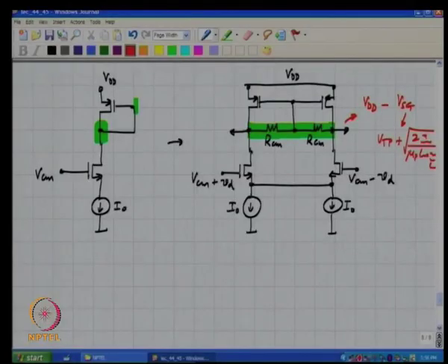Another way of measuring the common mode, for instance, would be to convert these voltages into currents, right, and add the two currents up, which now has information on the output common mode voltage in current form, compare it with the reference current either explicitly or implicitly, and use that information to tweak the gate voltage. Is this clear? Okay.